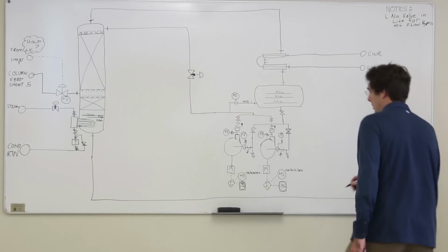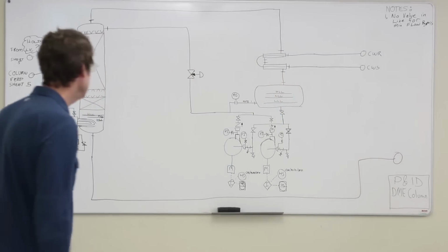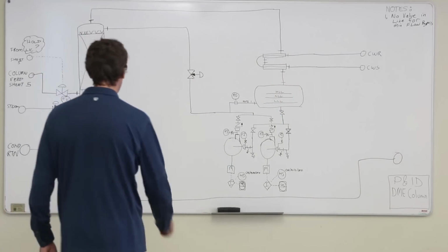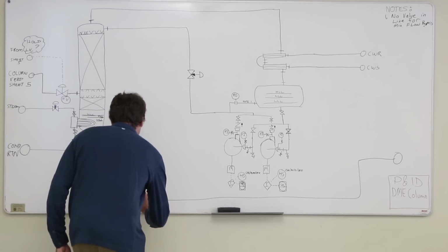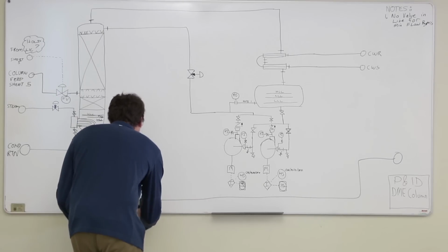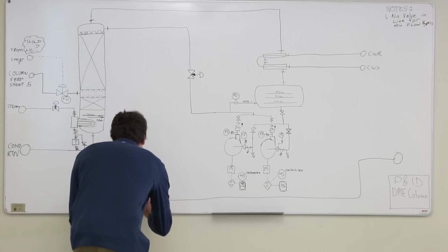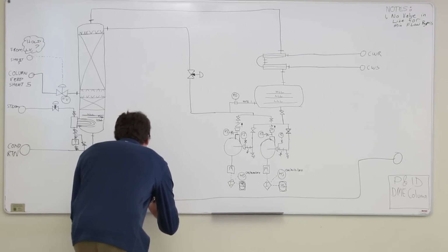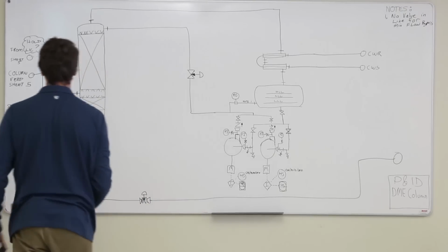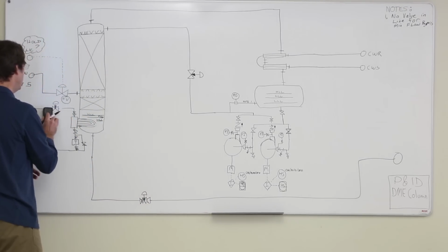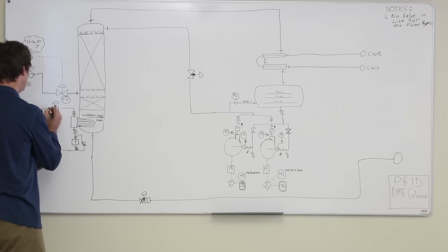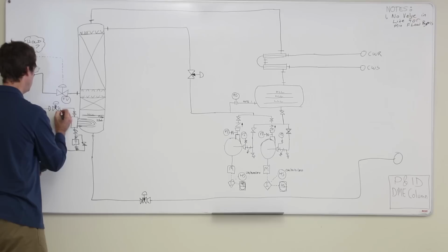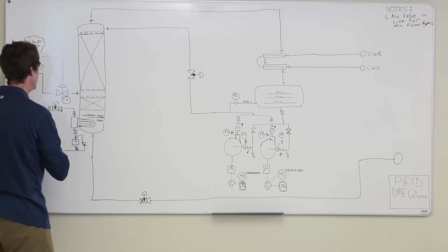There we go. Is it pretty level? We're for sure going to need a control valve in here. Most control valves have reducers around them, so I'm going to show the reducer like that. I should have showed the reducers on these as well. Like that. Probably going to need a reducer around this